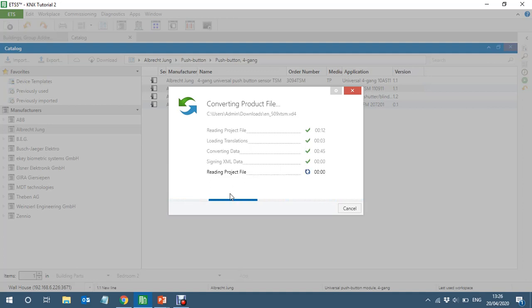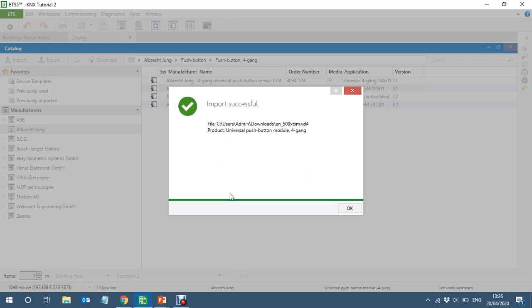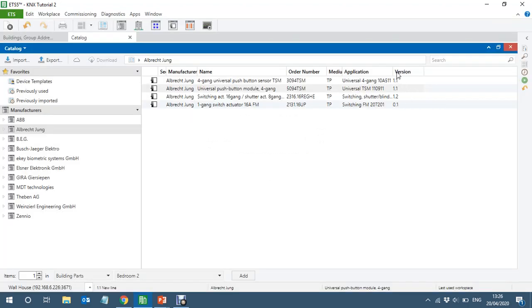But when you receive KNX devices, previously I had issues downloading the Yung devices. The problem was that when I received the devices, the firmware version was different. Like this is 1.1 and the device I had was 1.0, and I created the programming on 1.1.